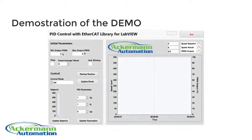Now we are going to run the demo application. For the DC motor we need to set the output limits of 20 to 100% PWM signal. Also, we enable the smoothing filter for the speed signal and the anti-windup.